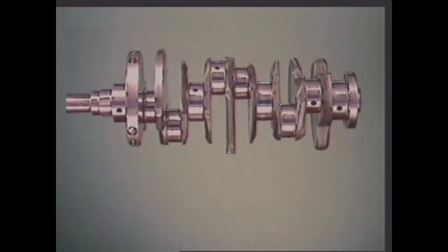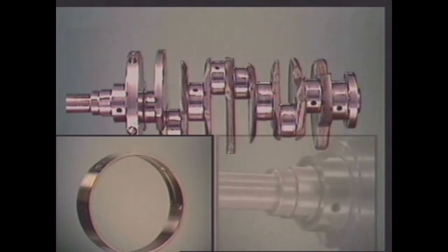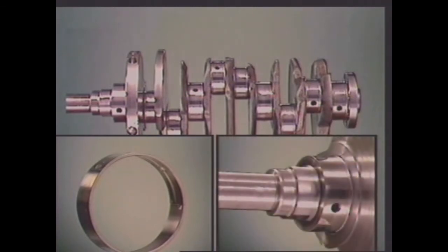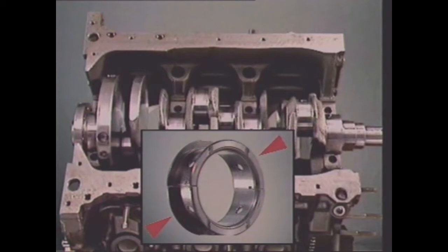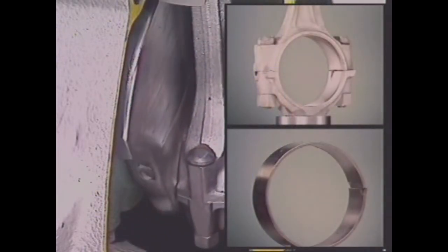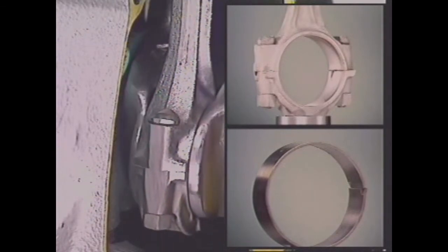The crankshaft is held in place in the engine block by main bearings at points called journals. Different bearings do different jobs. These bearings support the crankshaft in place but let it turn freely. The crankshaft also needs to be located to stop lateral movement. This is done by using flanges. Between the connecting rod and the crankshaft are connecting rod bearings. They protect the spinning crankshaft at points also called journals.